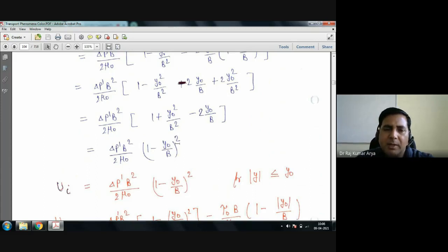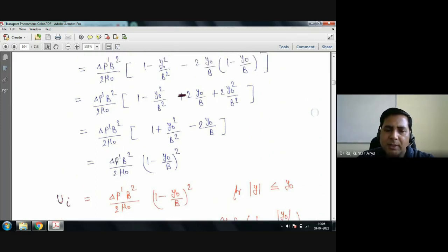Why did we do that part? Because these are known parameters. Tau b and so on are fluid properties, but once you take it, sometimes they may change. So you can put a pressure gauge at both ends, which can be measured much more correctly. Therefore, the shear stress expression is converted into delta P, which is an easily measurable quantity. Correct or not?